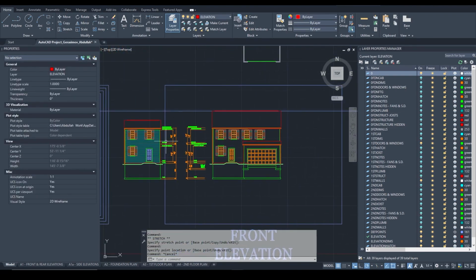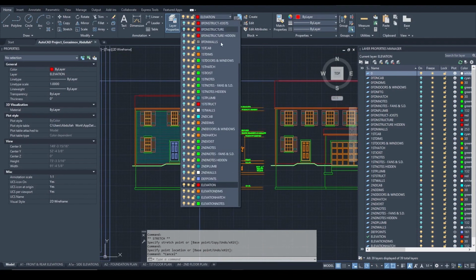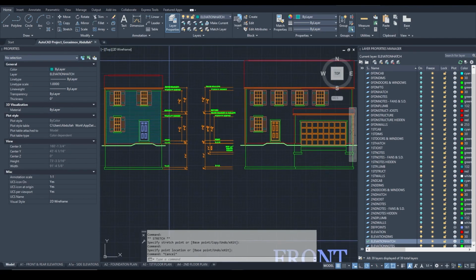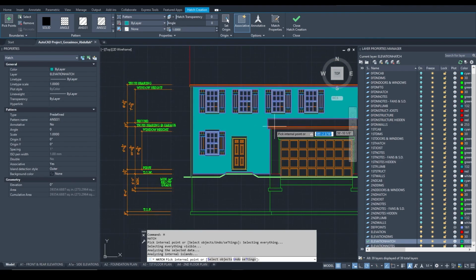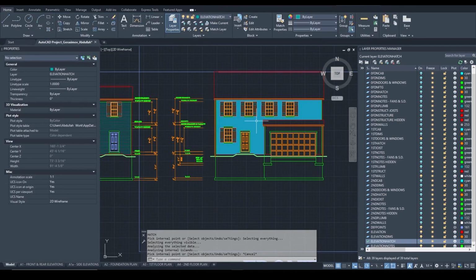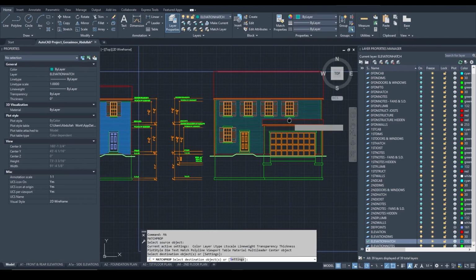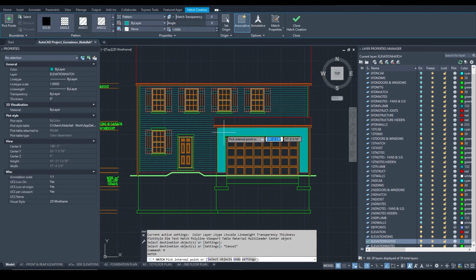Another thing we're going to work on right now is the hatch, which is probably one of the most exciting things. Let's go ahead and change the layer to the elevation hatch. Type in H for hatch. Put it in the front of the building first. And then let's match the properties of the elevation we've pulled in for reference, MA. Click on this and click on the one that we have drawn. And it copies and essentially matches the same attributes.